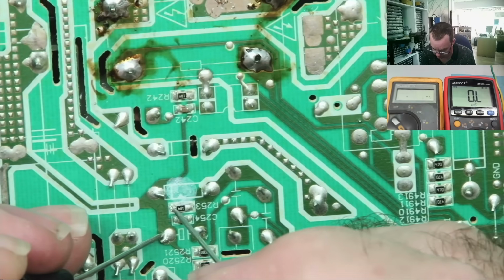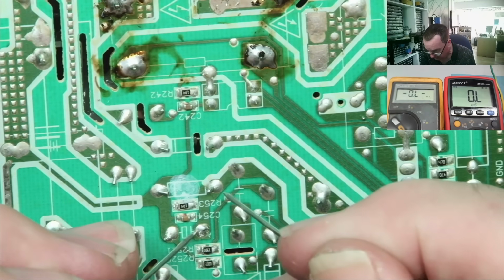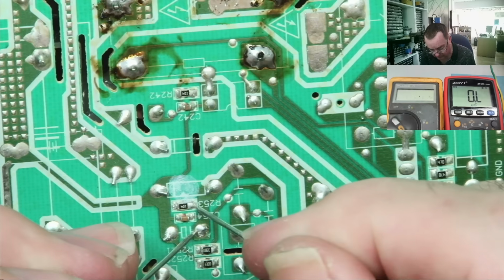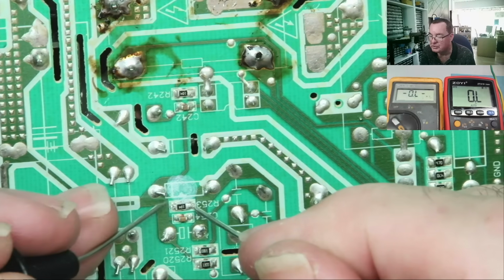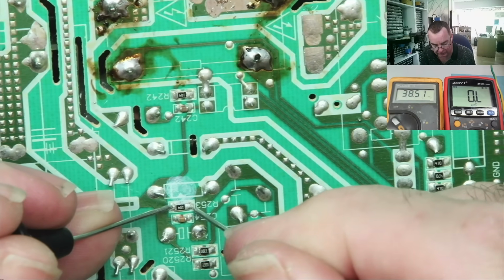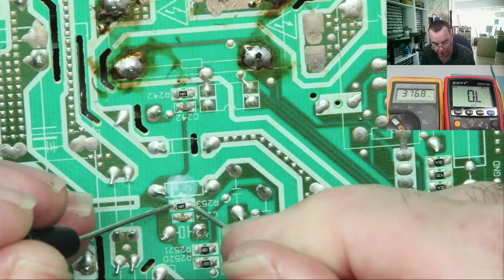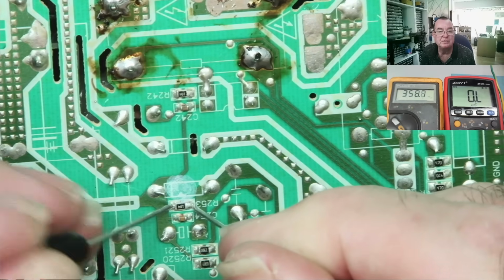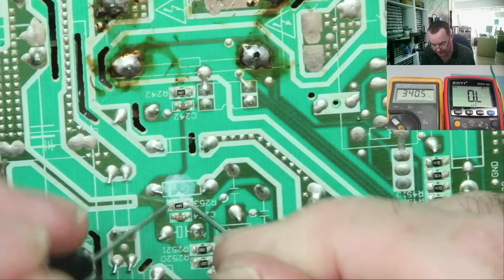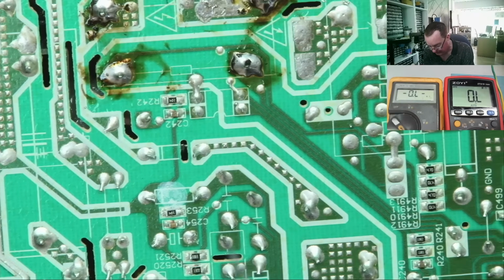That end goes to the capacitor, and this end goes to the capacitor. If I measure the resistor, you see it's counting 38k, 39k, 4. Then it goes to like 400k and starts coming downwards, and you think it's reading higher than it should. This is some peculiarity with the auto range when the capacitor is charging up.